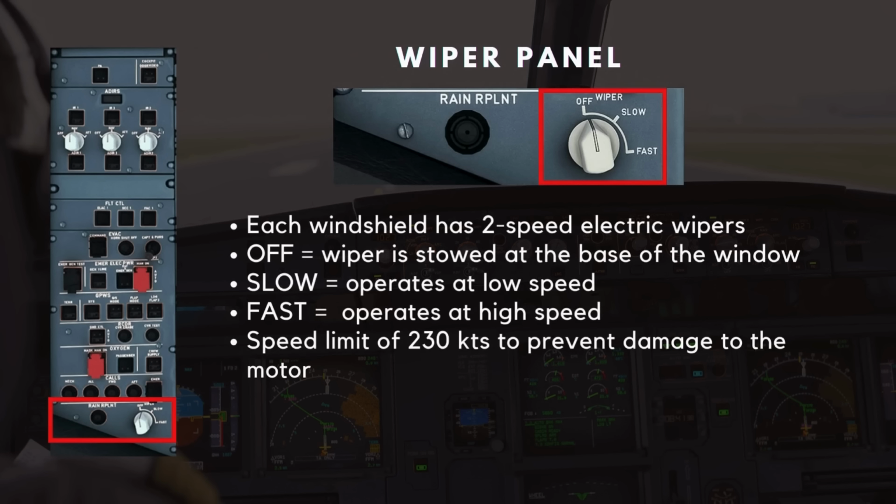First section is the wiper panel for CM1. Each windshield is provided with two-speed electric wipers that are controlled by their individual wiper selectors. With the wiper in the off position, the wiper is stowed out of view at the base of the window. When in the slow position, the wiper operates at low speed, and when in the fast position, the wiper operates at high speed. There is a speed limit of 230 knots to prevent damage to the motor.